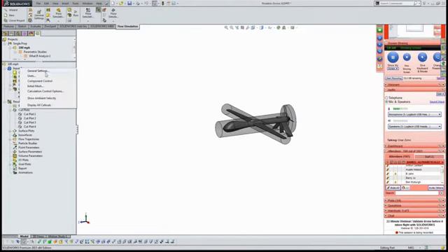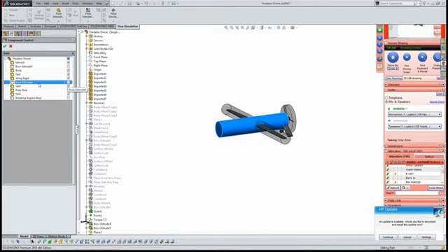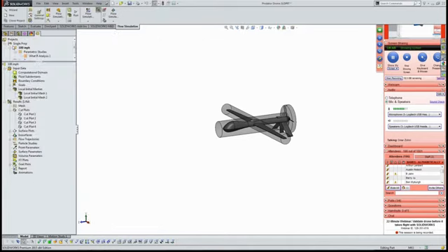In addition to that, I'm coming to my component controls and telling the solver, these bodies, do not include them. They're not solids. They're simply there for a mesh setting, or they could be a place where you wanted to monitor results. So you've got that kind of control. There are lots of different mesh controls that you can use.